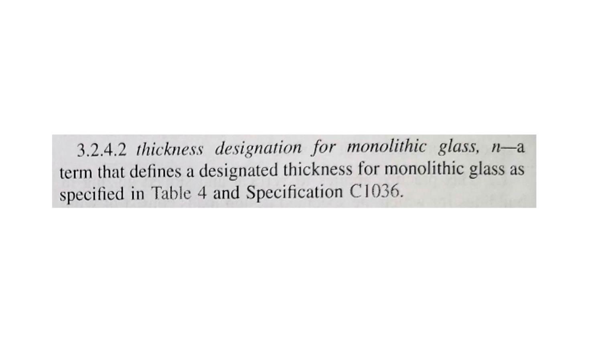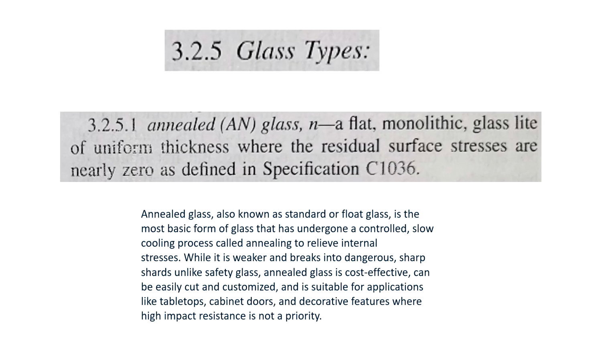And when we're doing our calculation, if we have to do a calculation, and they give us a nominal size, we're going to go to Table 4, and the next smallest number is what we're going to use in the right-hand column, just to be on the safe side and have a conservative number, they call it. Except in those exceptions, remember, that we talked about as well.